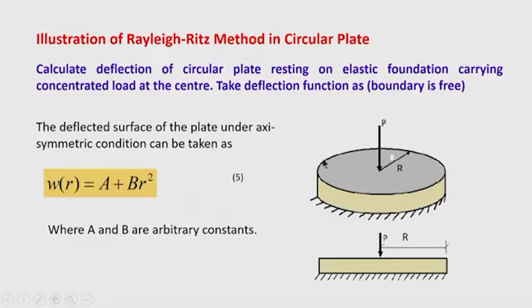If somebody wants to construct it, then this footing, this foundation slab, may be idealized or modeled as a plate which is resting on the elastic subgrade. So, the elastic subgrade here acts like a spring that offers resistance to the downward deflection of the plate subjected to vertical loading.